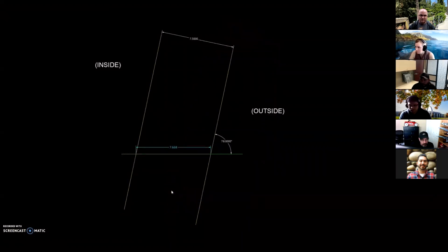Now that we have established, as mentioned before, the footprint shown with green line for the sloped elevation with a floor plan or horizontal dimension value of 7.668, we can create what I'm going to call the bottom footprint of the miter corner.